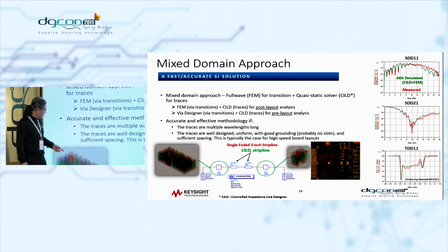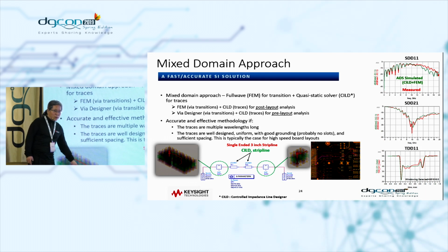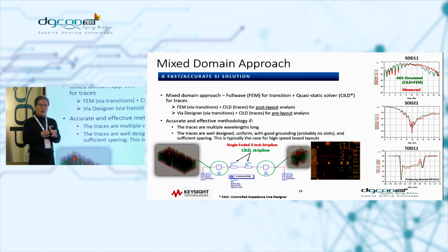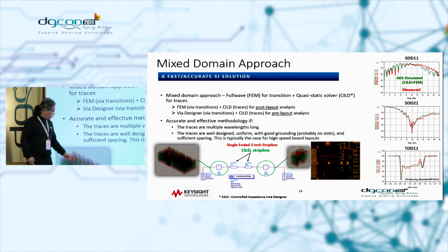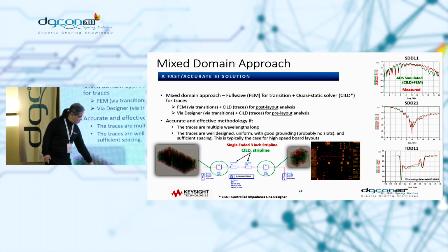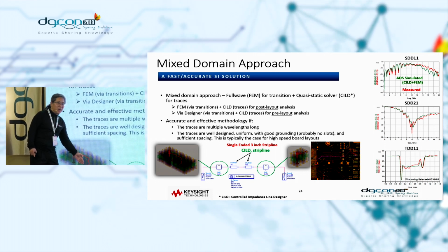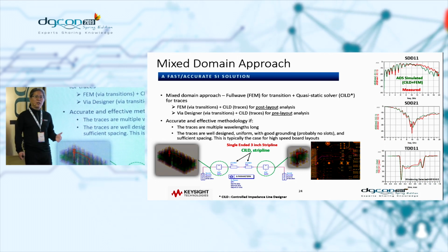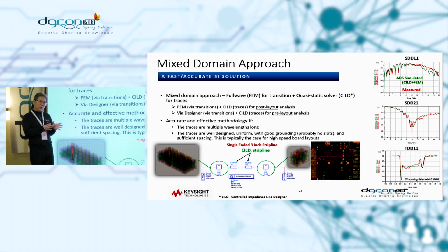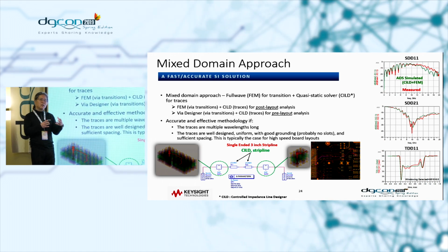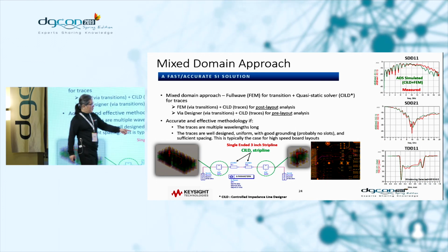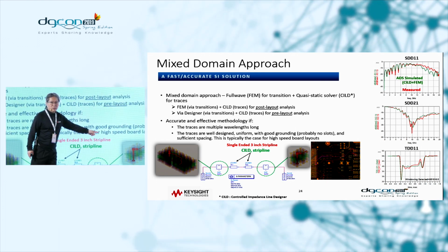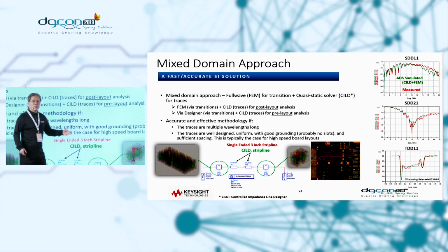Second, this section goes through a lot of BGA vias, where there will be coupling, right? So I'm maintaining the length of the line to the exit points of the BGA. That's one way of specifying the good size of the via transition. And the same for this one too. That was done in exactly the same way. So that's one way.